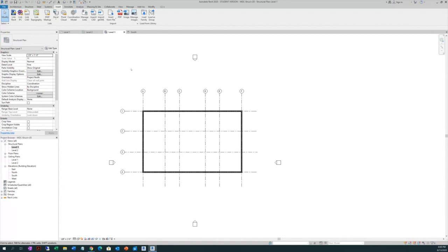You should always pin your link files, for security. But now, if I want to select or move something on my link or on my pinned element, I can't, because that is what this controls. It doesn't allow me unless I check select links up here.